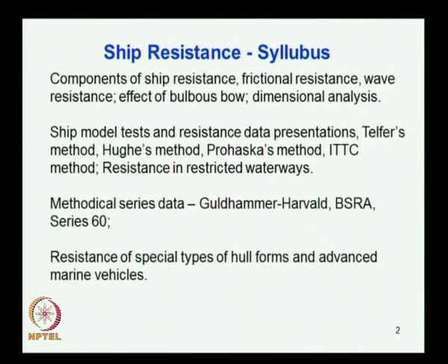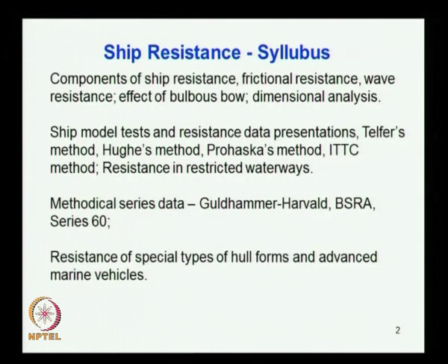Then ship model test and resistance data presentation, that is, how the model tests are carried out, how the data obtained from the model test are consolidated and presented for future design aspects, how you extrapolate from the model to the ship, and what are the discrepancies associated with this extrapolation from model to ship. The different methods covered include Telfer's method, Hughes method, Prohaska's method, ITTC method, and naturally